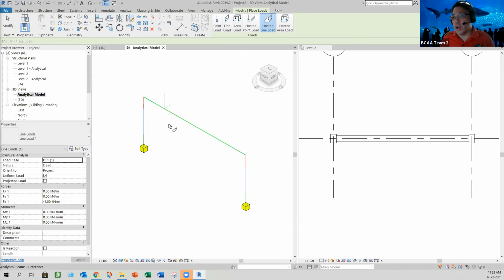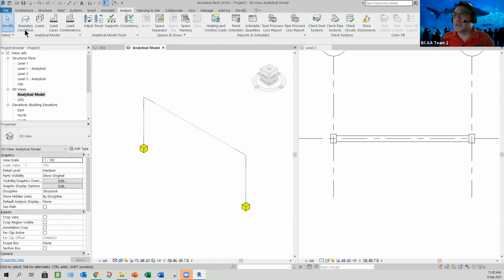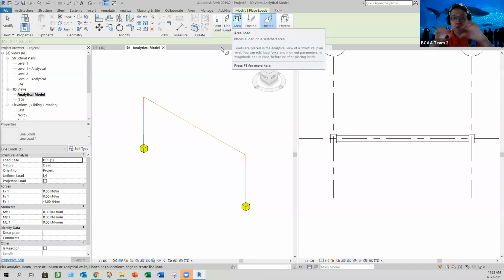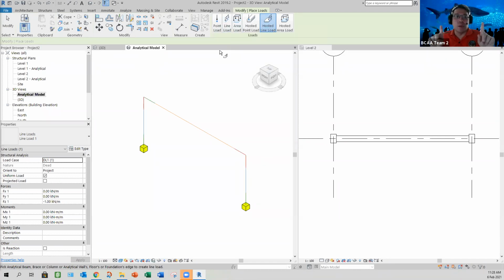Okay, then you define the loading you want. Sorry, just now I think I made a mistake. This is the boundary setting, which we defined already. As for this load distribution, it should be loading. And load, you can see you have point load, line load. But because you are hosted into this, all this is unless it's on its own, no column below. So for this line only, it should be hosted. All right. And of course, you need to set the loading you want.